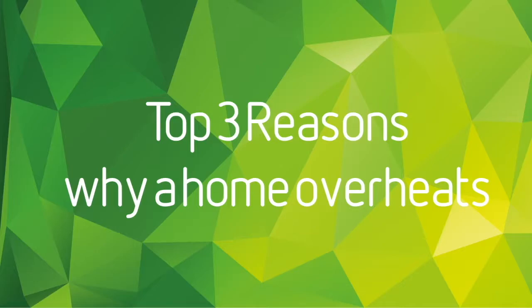months. Top 3 reasons why a home overheats. 1. Solar gain. Where you provide a lot of glazing, you get a lot of solar gain from the sun. The sun will provide a huge amount of gain during the day, and if there's no way of the energy dissipating, by the time someone comes home, the space will be very uncomfortable. Secondly, internal gains. Humans give off a lot of energy, plus your TVs, cooking, all that causes the space to overheat. The third reason is that the external air temperature has exceeded comfort levels.